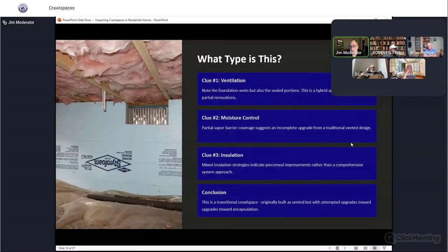We're going to get into report writing. We have 20 minutes left. We're going to run through this, but during this webinar, we're going to get into report writing and how to write these things up. But personally, when I write up my reports on something like that, I will put in the comment that this is not unusual for an antique home, that the support was solid, there was no movement of support. I'll write any decay or anything like that. I will put if nothing's underneath it, and that upgrades may be needed.